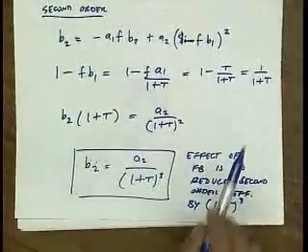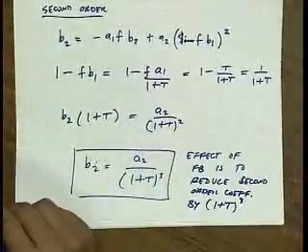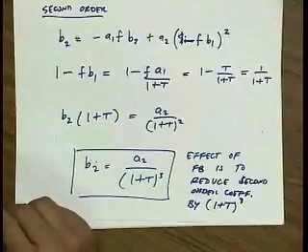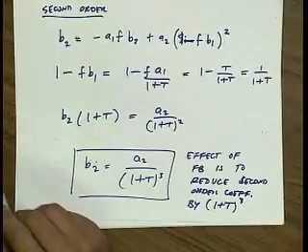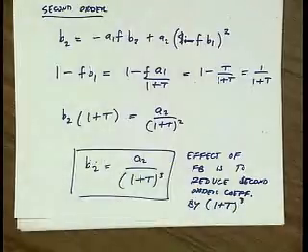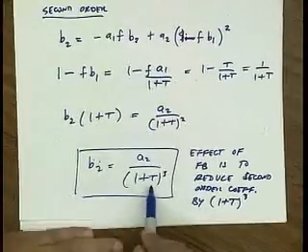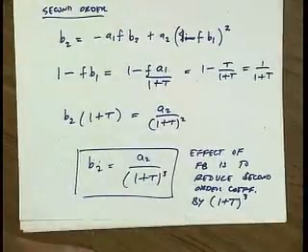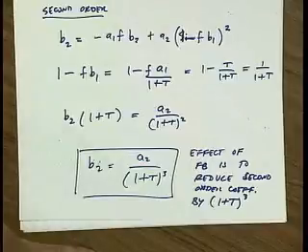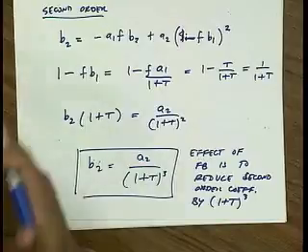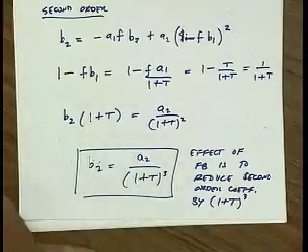I should also mention that we're doing this for a memoryless nonlinear system. Often our feedback network will have frequency dependence. Actually, the forward amplifier may also have some frequency dependence. It turns out, if you're careful, in most cases, if you make T a function of frequency, you still get the right answer. So even at a high frequency, as long as you take into account that the loop gain has dropped, you can still substitute here and figure out the effect. Okay.